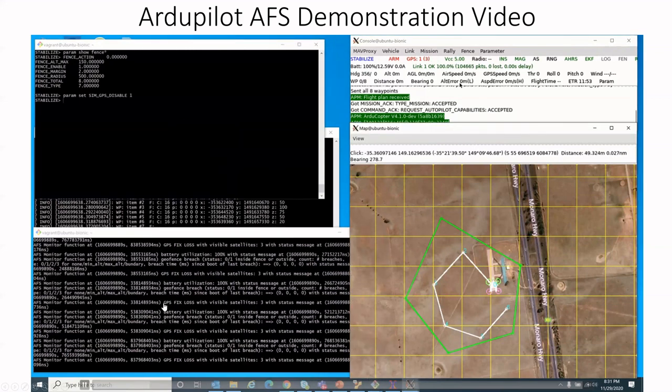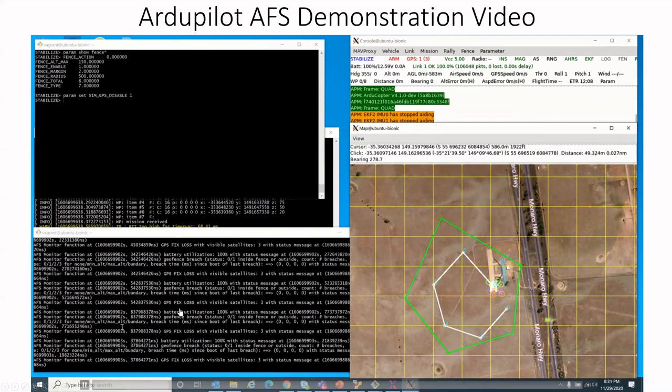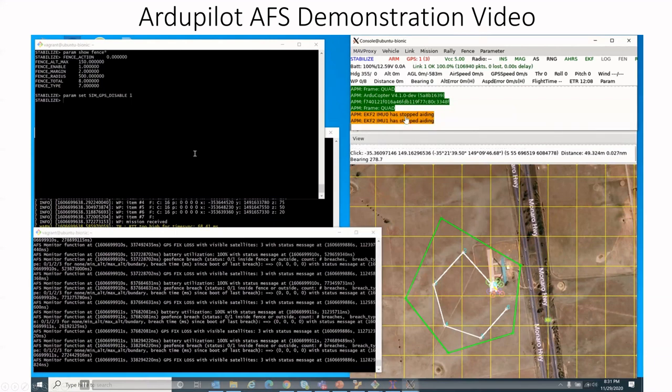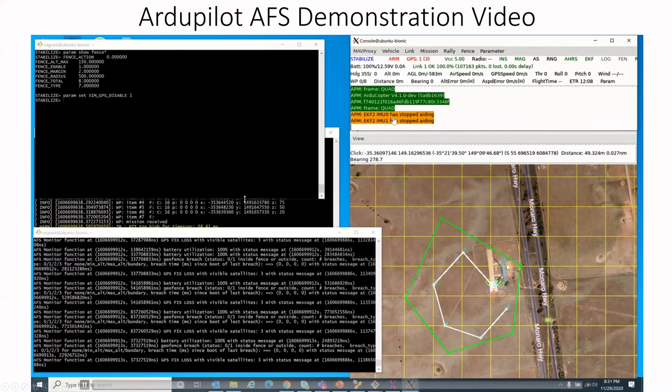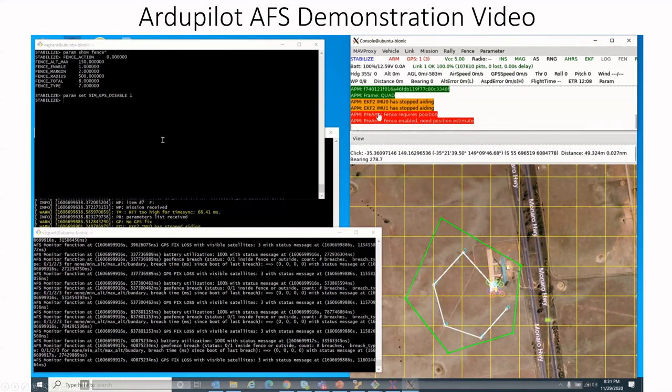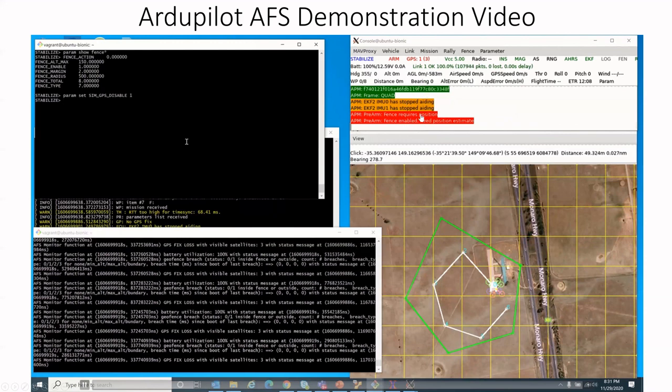And so it shows you that we have now disabled the GPS, and you can see the GPS fix loss is now being detected by the advanced failsafe monitoring function, the bottom left. And when you see the GPS being disabled, you can also immediately see the IMUs onboard the navigation system have stopped aiding the navigation function, so there is a problem with that.